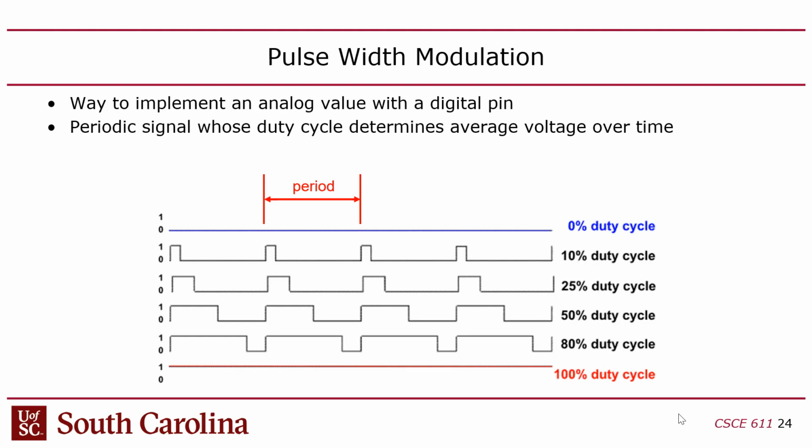So obviously PWM is limited to having an upper limit of whatever the 1 voltage is, right? So you can't output a big voltage, but if you use this to control something like an H bridge or a power electronic circuit, then you can end up achieving high voltages with this.